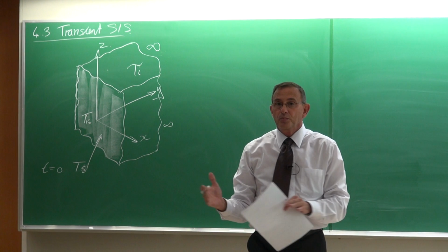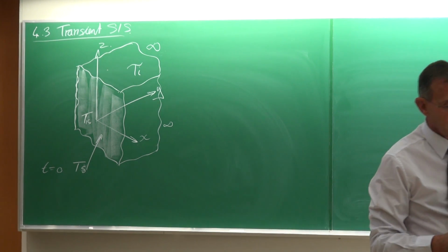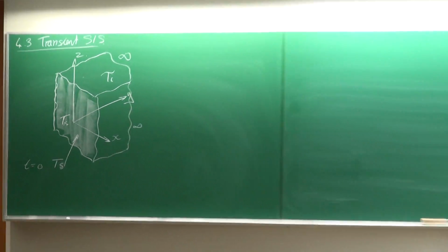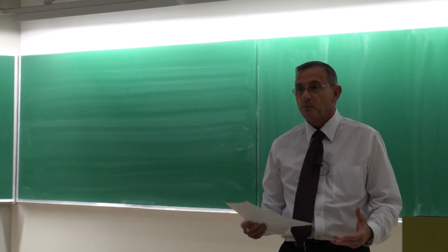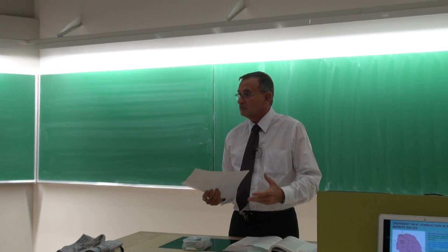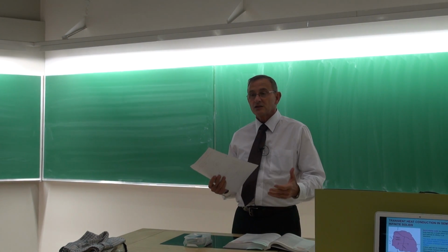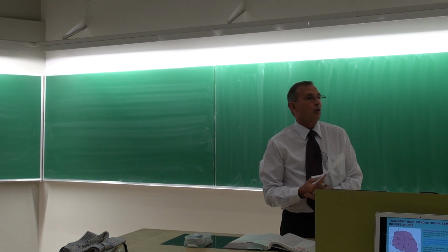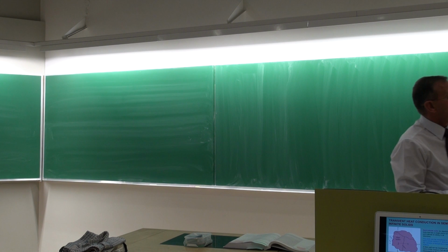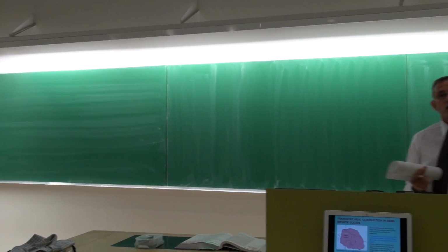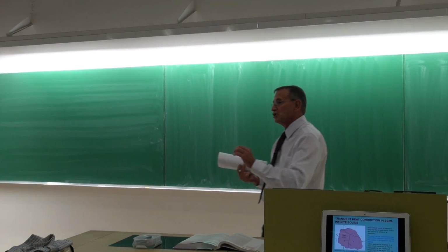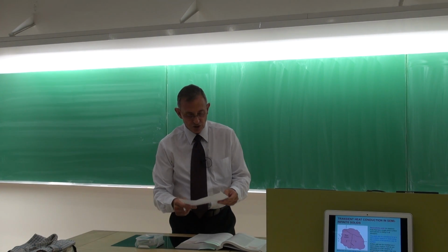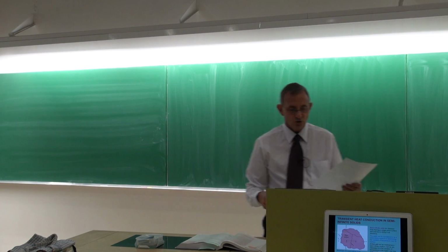The practical examples are, for example, cases where we want to look at the surface of the earth, maybe a water pipeline, if it is going to freeze. That is one practical application. And other practical applications are almost any big body or relatively big body where we want to know how the temperature changes very close to the surface. That would also be valid to use the semi-infinite solid approach.